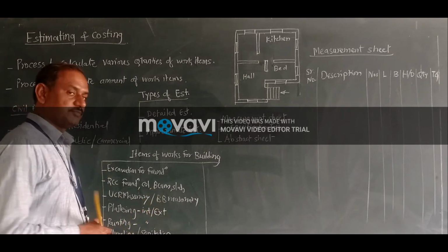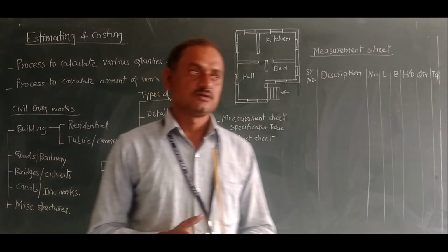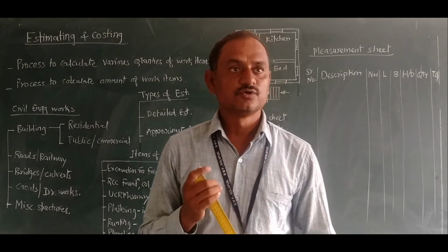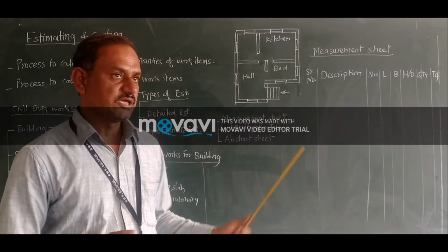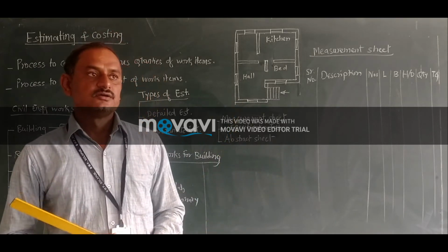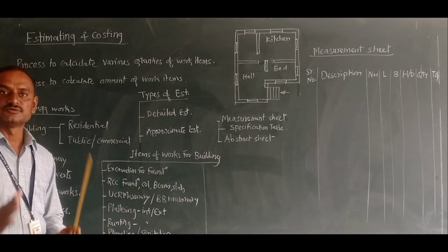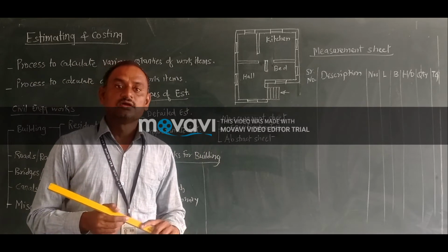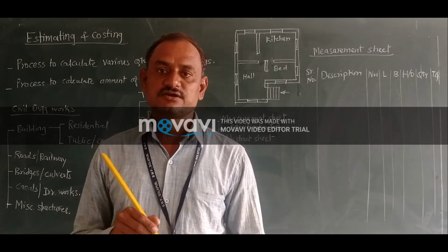That is called brick masonry. So UCR masonry generally has various sizes, like 0.45 meter in width and at the max 1.2 meter in height for construction, and for making a plan for a building. So the learners should know all the sizes, thickness, and the minimum sizes which are given in the specification table which is given by our IS code, that is Indian Standard provision.